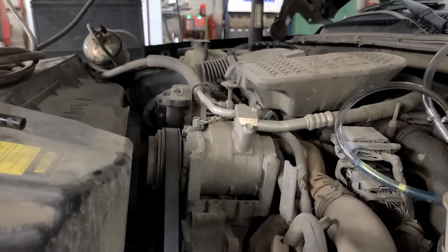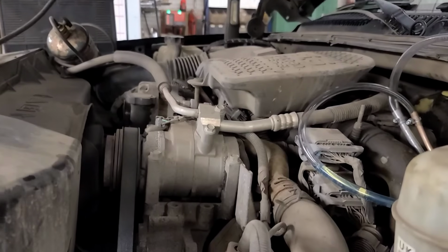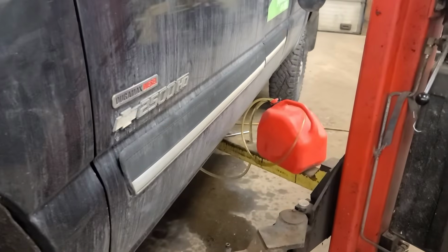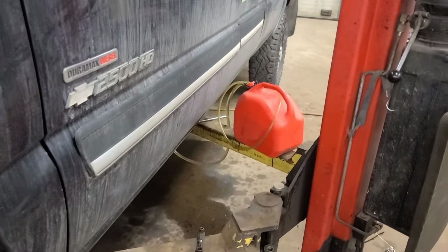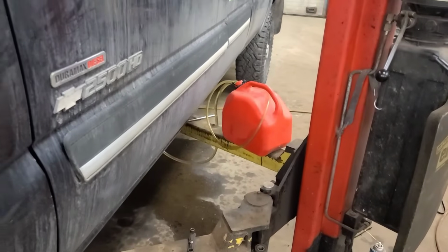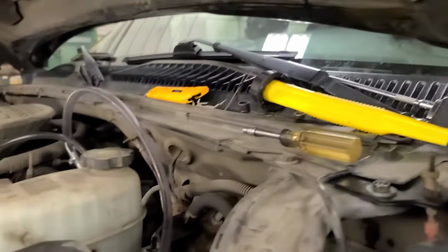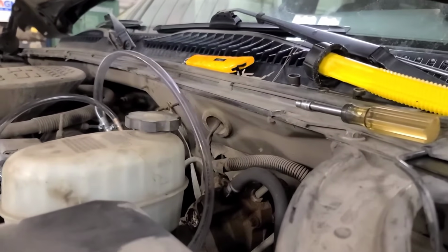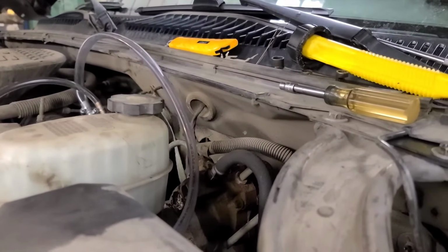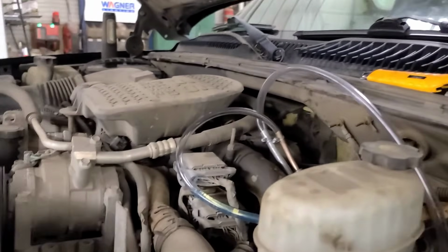So I've tried bleeding this thing 6 times. I get fuel, but it's not consistent. I took the fuel tank out of the equation now, and I connected the gas can here, and I still can't get it to bleed. So I'm starting to believe that there's a suction leak in that line. I wonder if it's leaking where that union was put in aftermarket. I'm thinking about just running a new line.